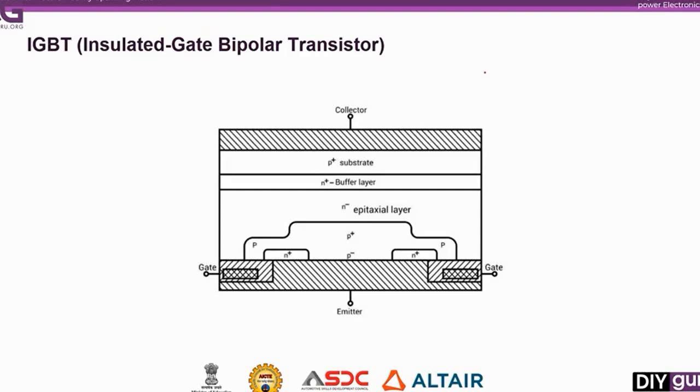A peculiar phenomenon is observed in IGBT. This is known as the latching up of IGBT. It occurs when the collector current exceeds a certain predetermined threshold value. In this case, the parasitic thyristor will get latched up and the gate terminal loses control over the collector current, and the IGBT will fail to turn off even when the gate potential is reduced below a certain voltage.